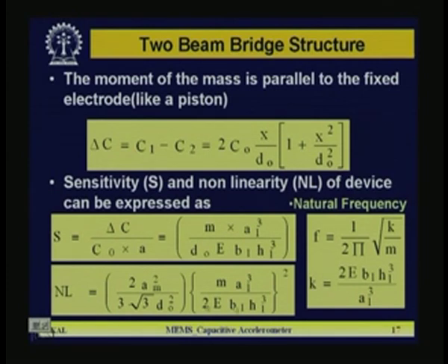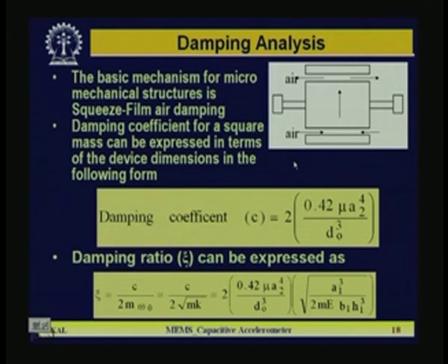These are the relations of sensitivity, nonlinearity, and change of capacitance, that is differential capacitance, in case of the two-beam bridge structure. Now, next is coming the damping analysis. Damping analysis is also important for the stability of the structure, and there we always think of the squeeze